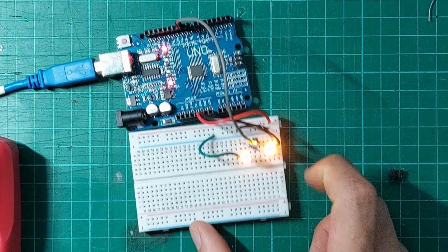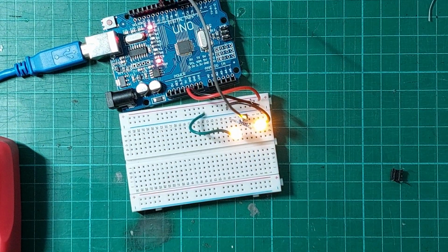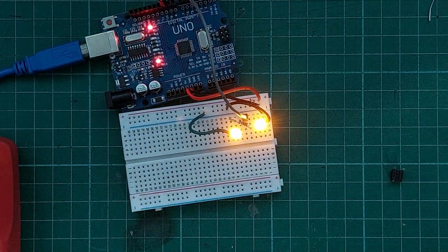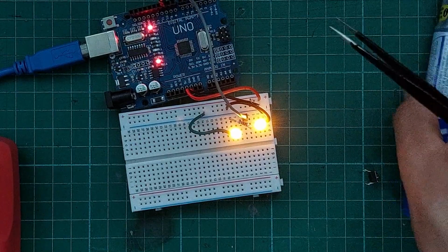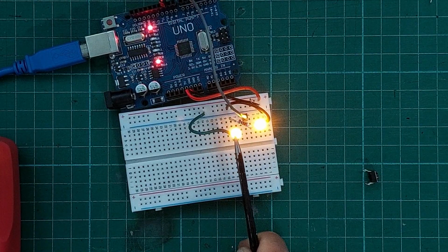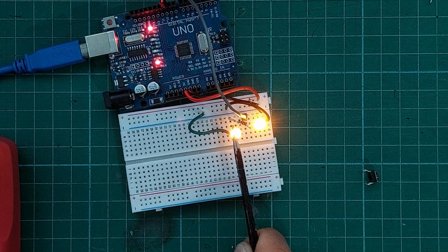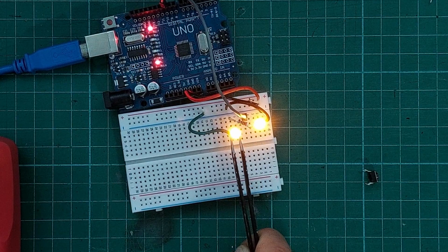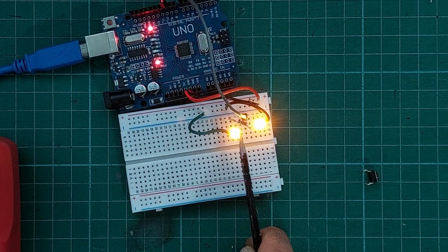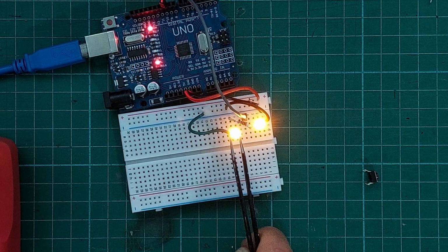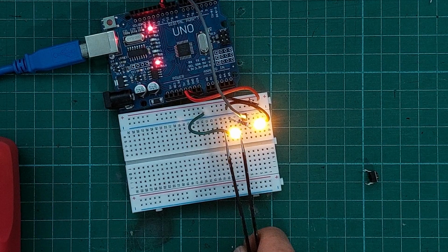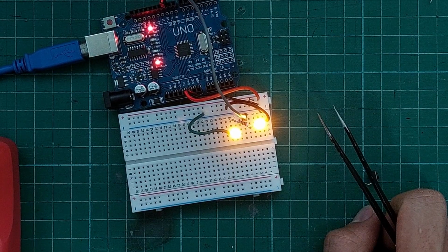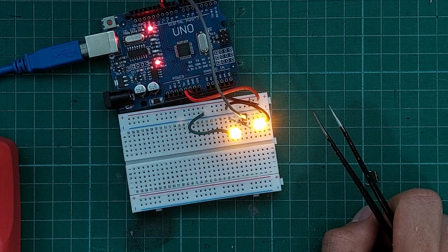Okay, so I don't know if you can tell. Maybe I should turn off the lights. I can zoom in. We can see that this LED, which is the one that we put on half brightness, is somewhat half the brightness of this. It's not that easy to tell on camera, but from my perspective, it's around halfway there. So that's how we know that this PWM thing is working, because the brightness is going to be half, since half the time the LED is off, or approximately half the time.